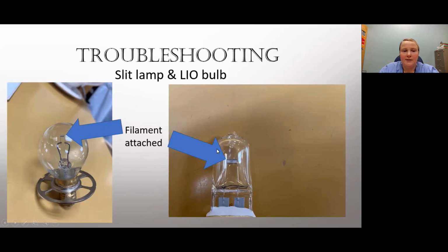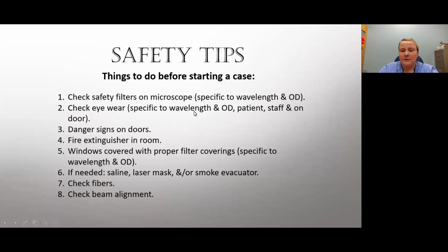You can also do a resistance check if you wanted to get your voltmeter out and do a check. If you can't see the filament, you can do a quick check with that for the resistance.